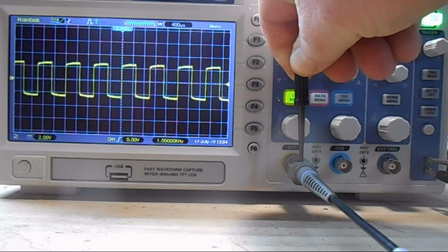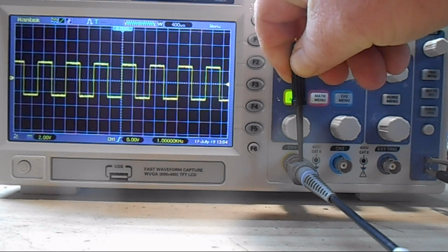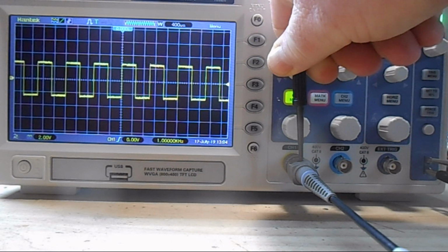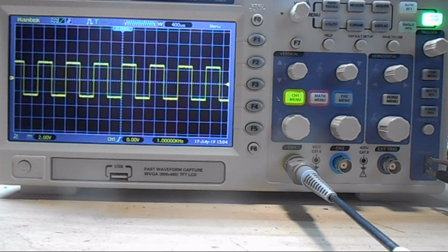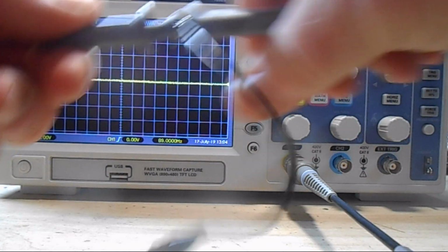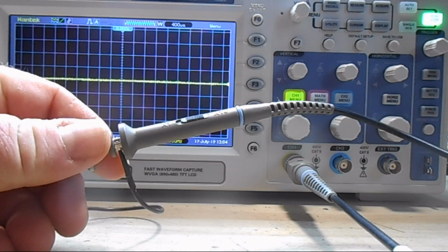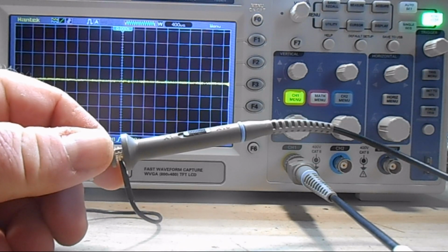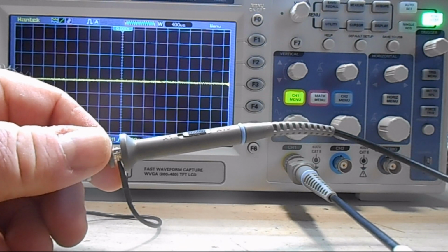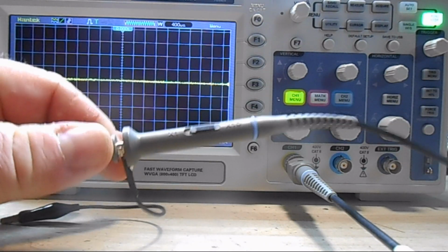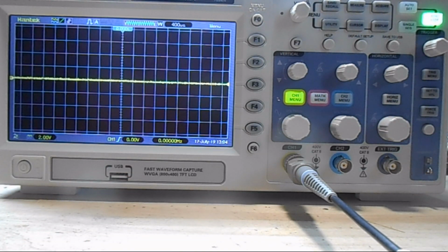So what we want is to get as flat a line and as parallel a line on the top and bottom as we possibly can. Now again, what we talked about earlier, the switchable 10x 1x, and I told you unless you have a specific reason, leave it on the 1x or leave it on the 10x. Dave Jones at EEVblog did a terrific video explaining why, so I'm not going to reinvent the wheel here and will just send you off to his video. I'll put a link to it down below.